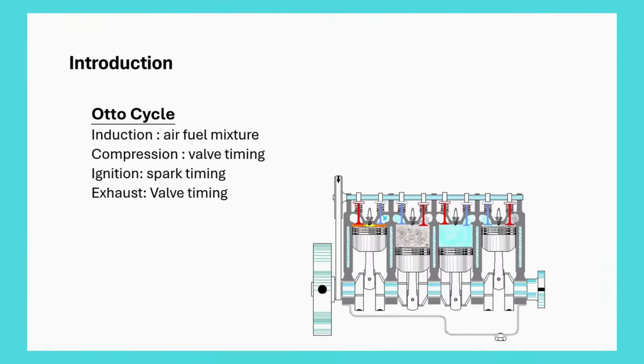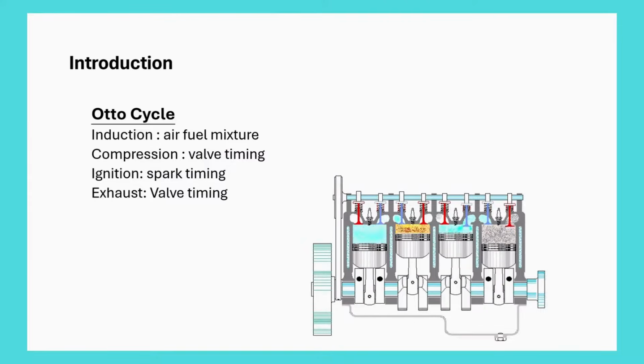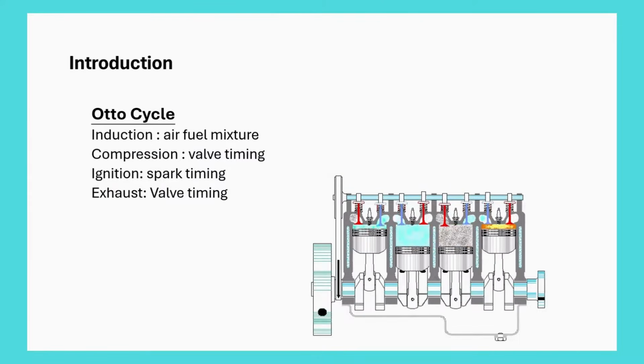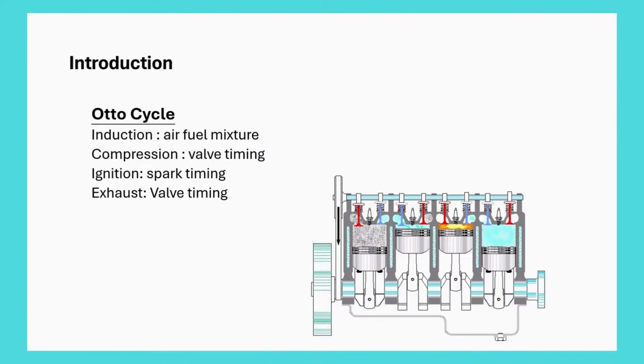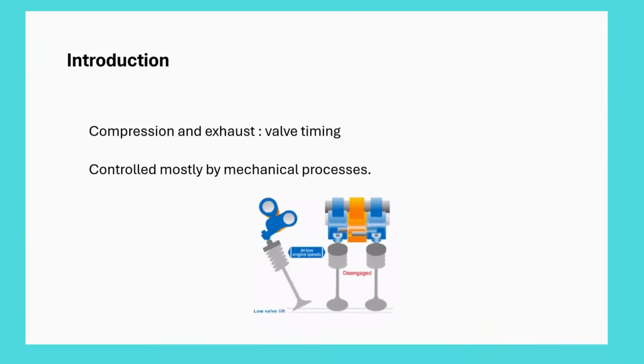Induction is dependent on the air-fuel mixture, compression mainly on valve timing, ignition on spark timing, and exhaust once again on valve timing. Compression and exhaust are dependent on valve timing. Valve timing is controlled mostly by mechanical processes.